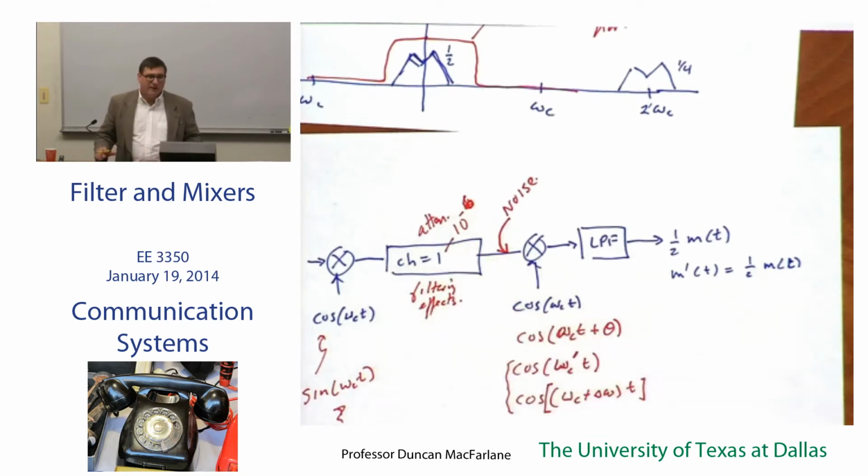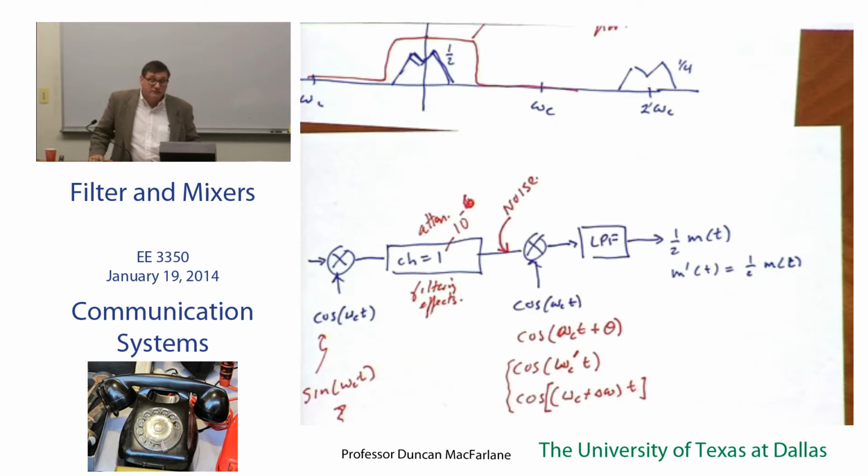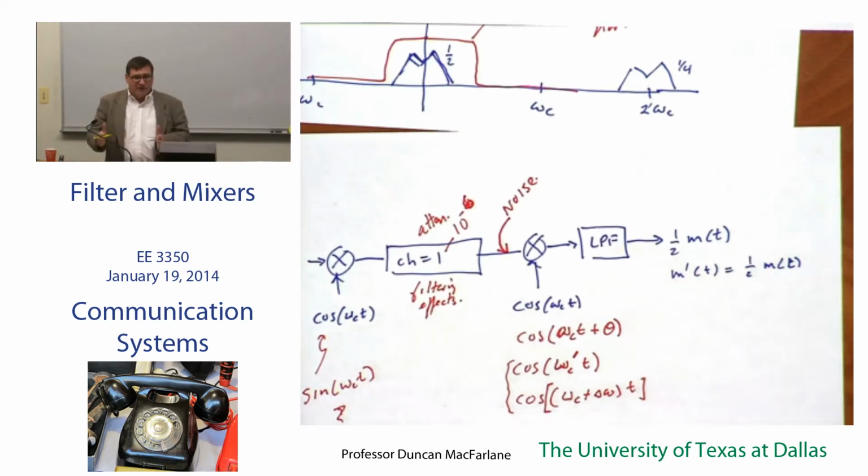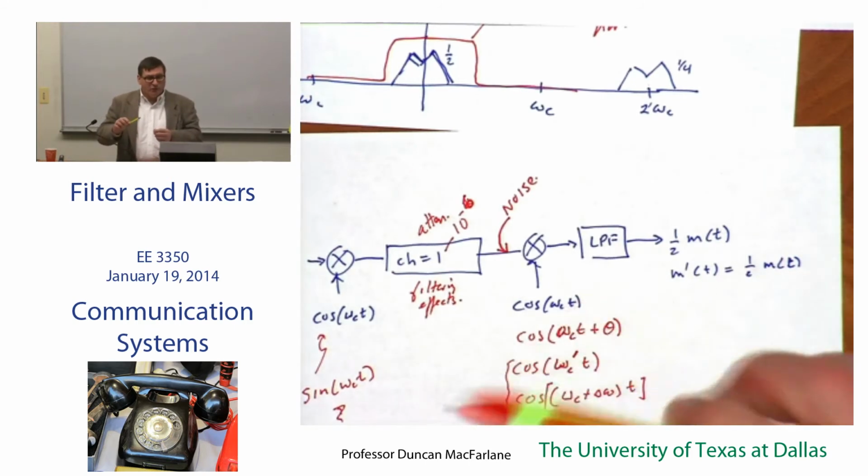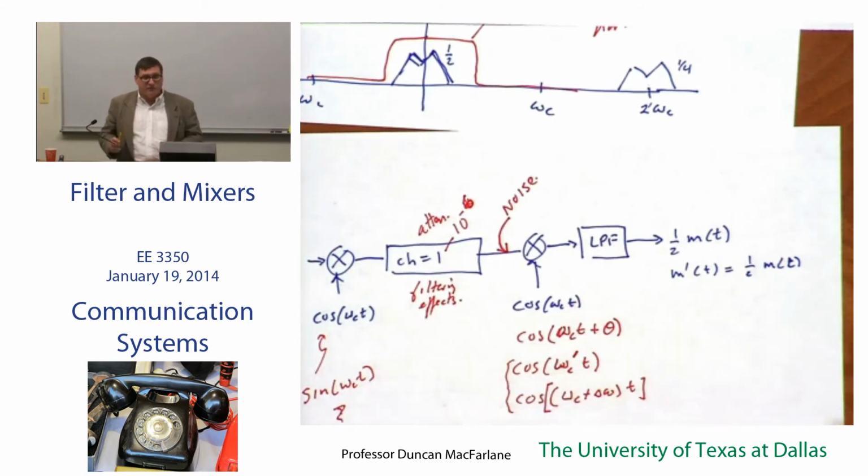So what else could happen in that channel? Time shifting. Time shifting would be a phase delay. Okay. Time shifting is a phase delay if I normalize every time shift to a frequency. Right? I'll harp on that again over the course of the semester. I find it easier to consider group delays instead of phases, and one is the derivative of the other.